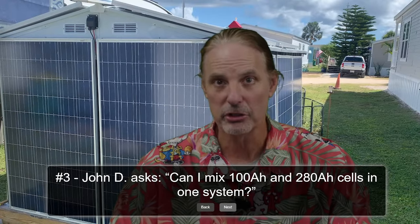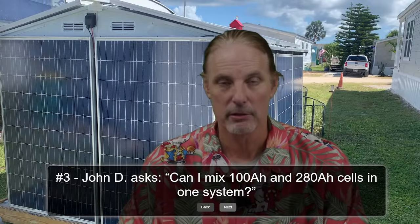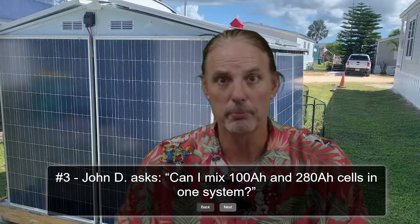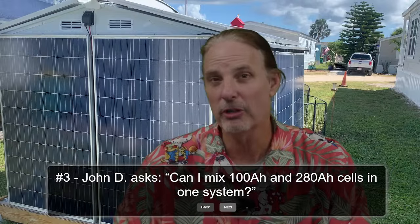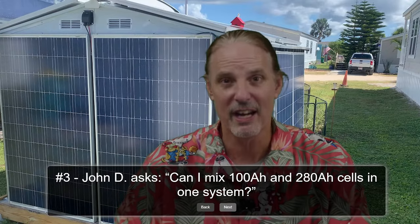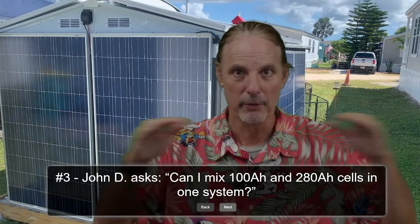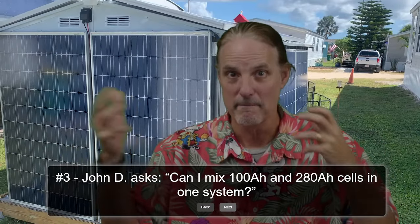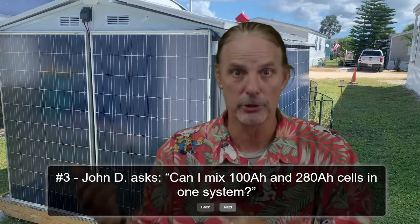There are mixed feelings in the market about whether or not you should do it. My opinion is that every battery should be fused properly to handle its influx and outflux of power. When they are hooked up into a bank, they should be very carefully balanced. I don't mean perfectly balanced, I mean balanced at the same voltage, so that when you turn them on, you prevent large quantities of power transferring from one battery to another.